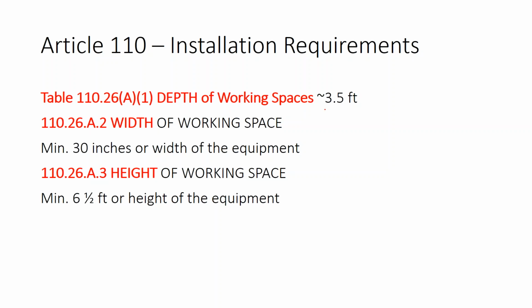And so one issue that we ran into was that not only do you have to have the batteries, they have to be accessible so that you can maintain them. With lead acid batteries, you're watering them and checking the electrolyte levels. And if you can't access 3 out of the 4 sides of the battery, that's not an accessible battery. Now, we bought a watering kit so that we don't need to water the batteries except at one point.